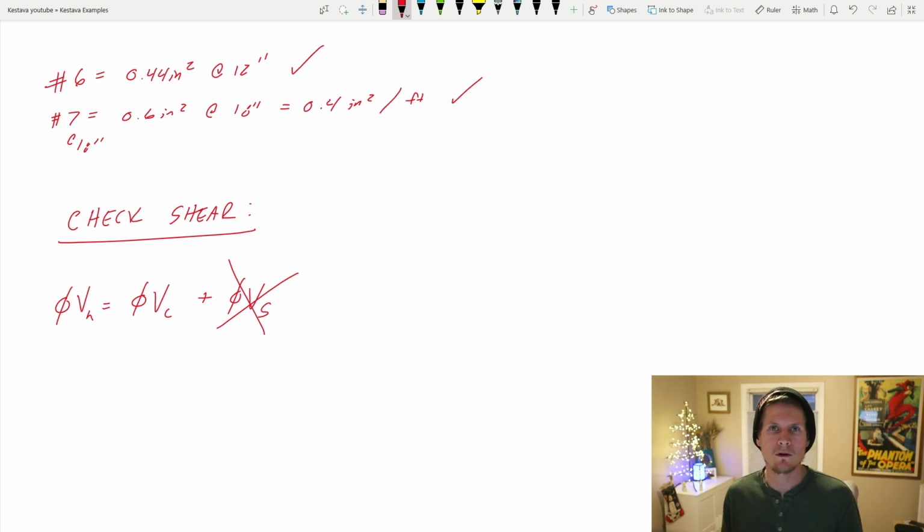If you ever design something like that, you should be talking with your project manager or your principal, because that is very, very uncommon, really hard to construct, expensive to construct. But I obviously don't know every scenario for retaining structures, so there may be instances where that's absolutely applicable. But if we find out that we don't have enough shear capacity just from the concrete alone, ultimately I wouldn't insert steel. I would increase the thickness of that stem to make things work out.